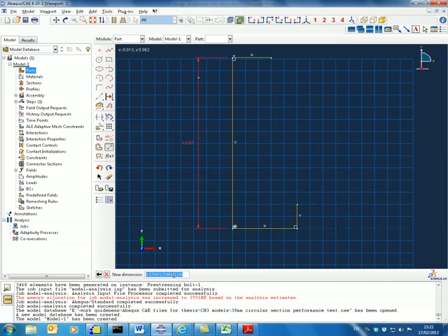As we have said before, the total length is 70 millimeter, the base is 19 millimeter in radius, and the height of the base is 50 millimeter. The output surface is 10 millimeter in radius, and it has a section which is used to hold the other parts to the front of the transducer, which is also 10.